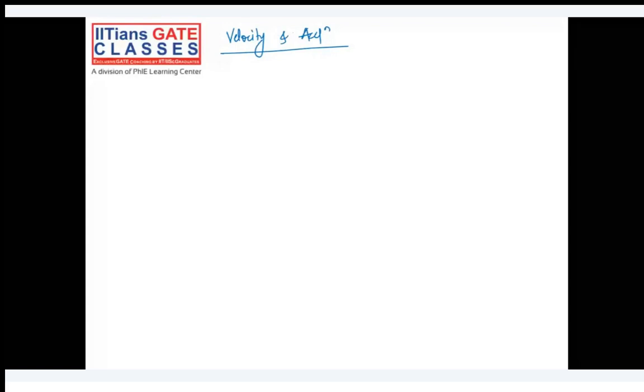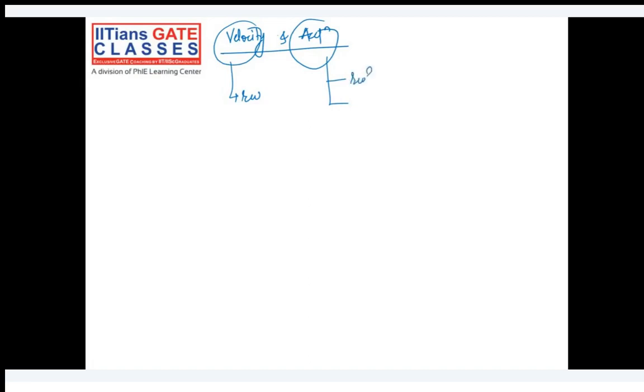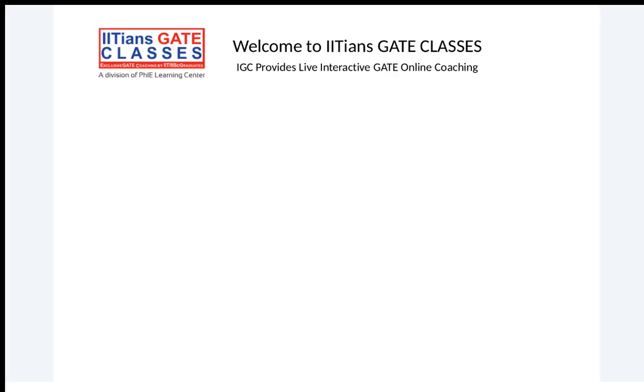And then we have studied the turn slide pair. Okay, so this is for the turning pair. For the sliding pair, it is very straightforward. The velocity or acceleration will be in the direction, or just opposite to the direction, of the slider, depending on whether it's acceleration or deceleration. So it's not difficult in that case. But if we have a turning pair, acceleration has two components: one is centripetal acceleration and the other is tangential acceleration.